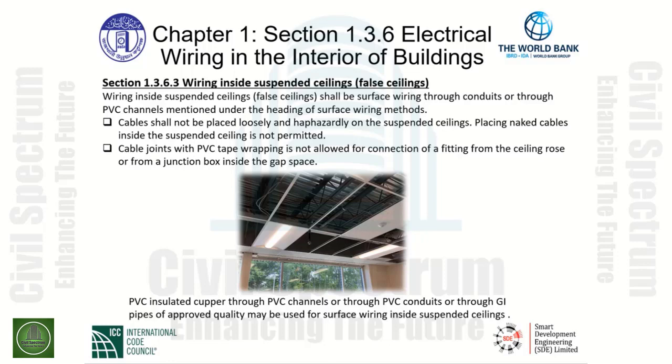As seen here, the picture indicates a suspended ceiling, which is dropped down from the structural ceiling and provides a space for wiring. It also provides a space for plumbing and mechanical ductwork and piping as well. We can use the surface wiring methods to wire in lighting from above this particular space.